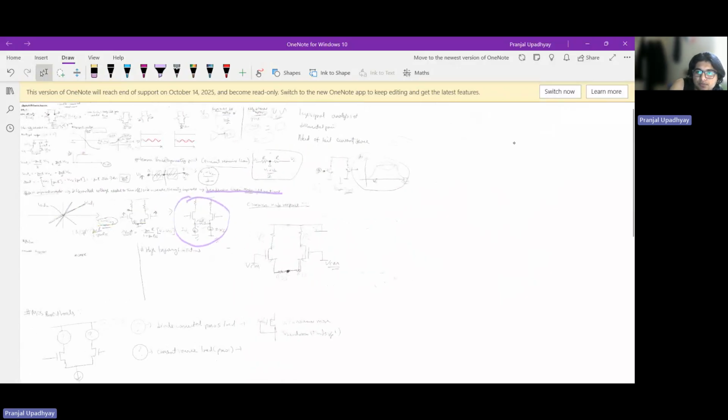So if I were to write, benefit number one was the range: the range of gain for Vin or V common mode basically increases. And number two is that it decreases ACM. Let us say the tail current source was not ideal and had some resistance, say Rx.